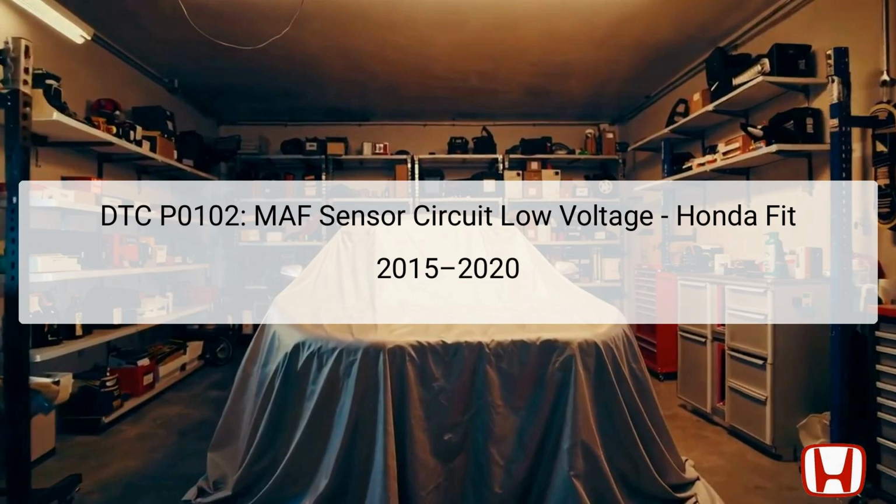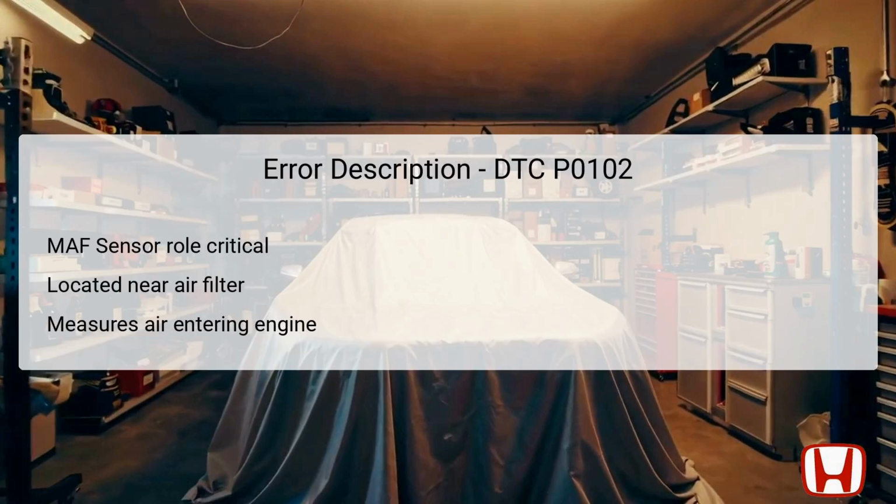The MAF sensor, crucial for engine operation, measures the volume and density of air entering the engine to help determine the correct fuel-to-air ratio. It is positioned in the intake duct, right after the air filter, to ensure it measures unimpeded airflow.